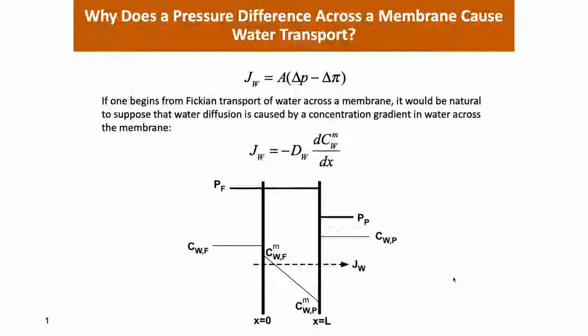And this problem was ultimately resolved by one of our faculty members here, Don Paul, who really put the nail in the coffin of the pore flow people with this basic chemical engineering analysis of how a pressure gradient induces a concentration gradient inside the material and ultimately flow.